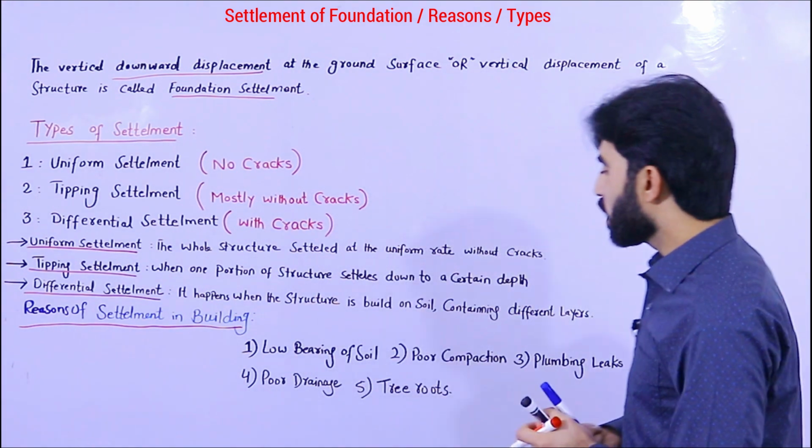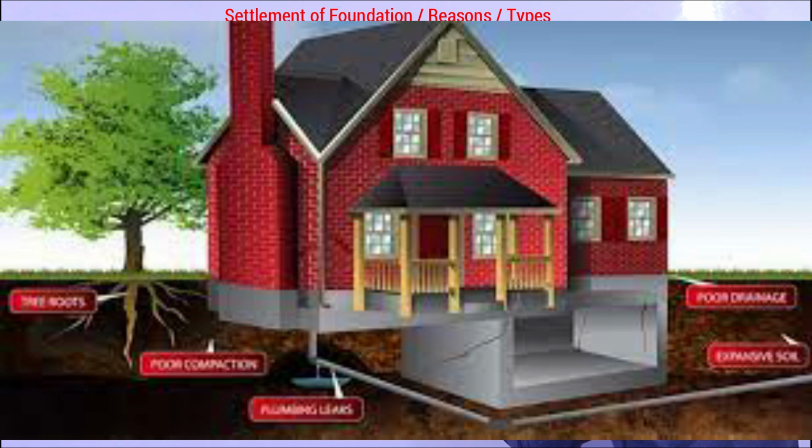The second one, guys, is poor compaction of soil. If you don't compact the soil, then after some time or during building construction the soil can settle inside the foundation. So compaction is very important. Poor compaction is also a reason of settlement in foundation.